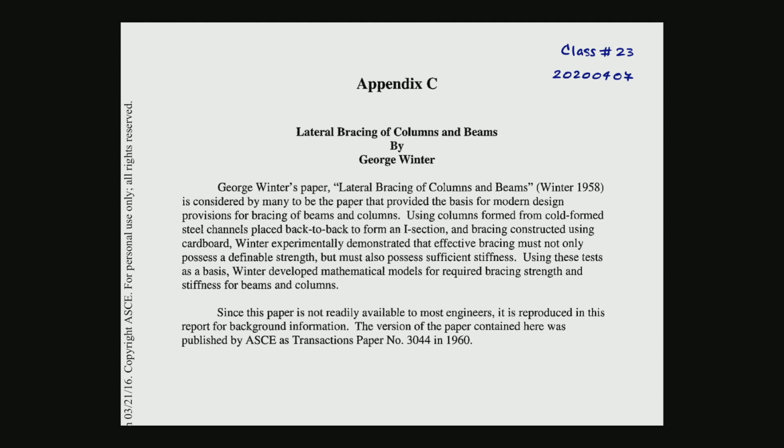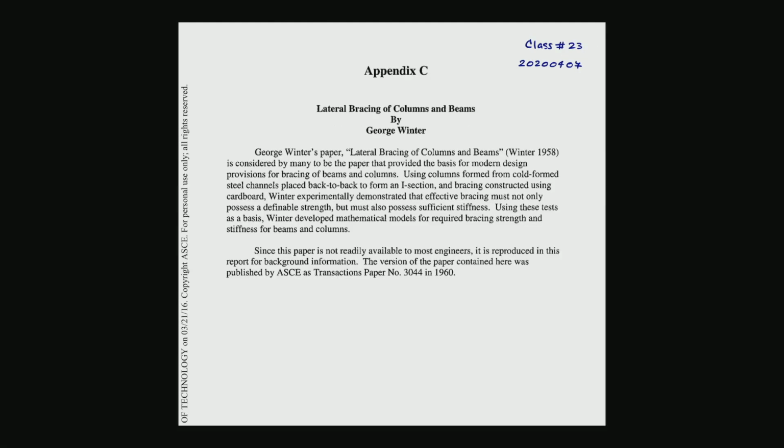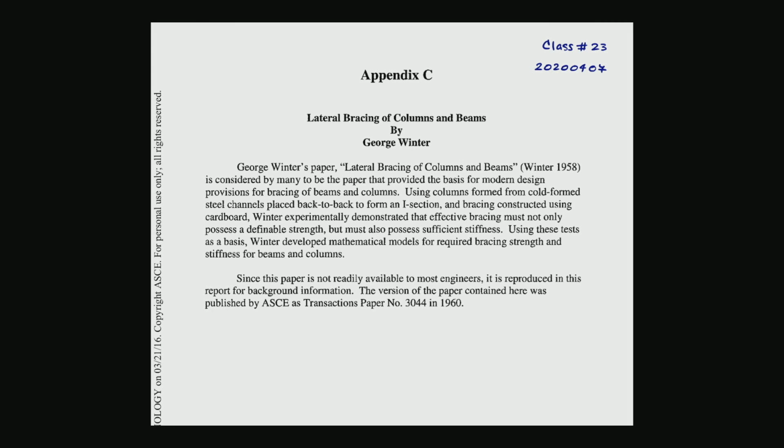And here is a very important issue. You know how to design the column, you know how to design the beam, but the brace is going to enhance the capacity, or ensure that you are going to achieve the capacity you wish to have from the beam or column, by the appropriate sizing of the brace.